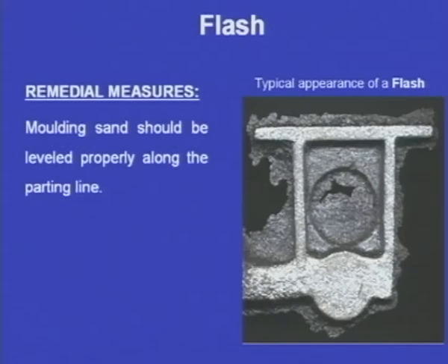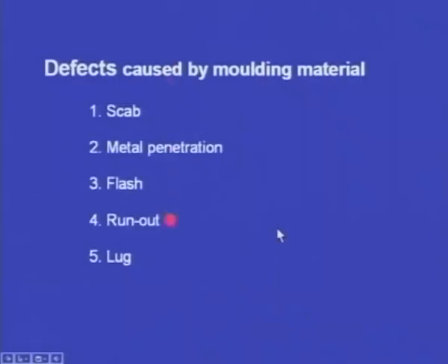And what are the remedial measures? Molding sand should be leveled properly along the parting line. There should be no gap between cope and drag along the parting line. Then this kind of flash will not arise. Next let us see the runout in this classification.